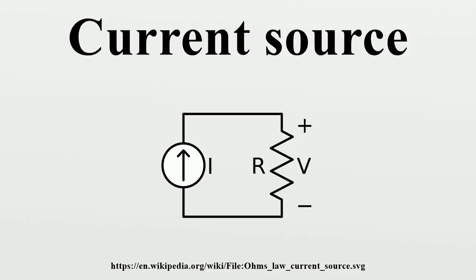A Zener diode, when reverse biased, has a constant voltage drop across it irrespective of the current flowing through it. Thus, as long as the Zener current is above a certain level, the voltage across the Zener diode will be constant. Resistor R1 supplies the Zener current and the base current of the NPN transistor. The constant Zener voltage is applied across the base of Q1 and emitter resistor R2. Voltage across R2 is given by VZ - VBE, where VBE is the base-emitter drop of Q1.